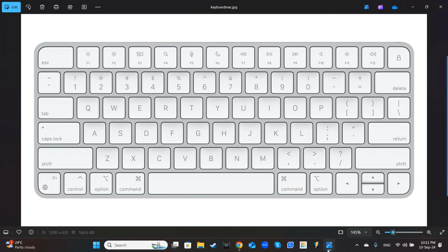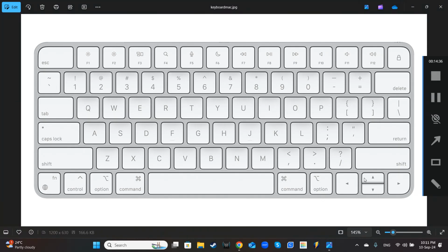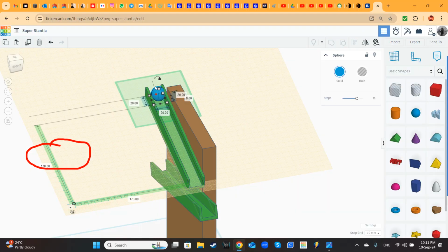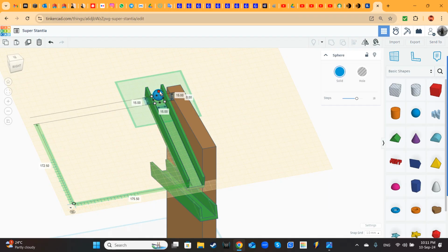Remember, if you want to make something small in a proportional way, if you want to scale the object, you have to change it with the handles while holding Shift. So I have the handles. I keep pressing Shift. And now I move. Shift is still here. I think it will do.